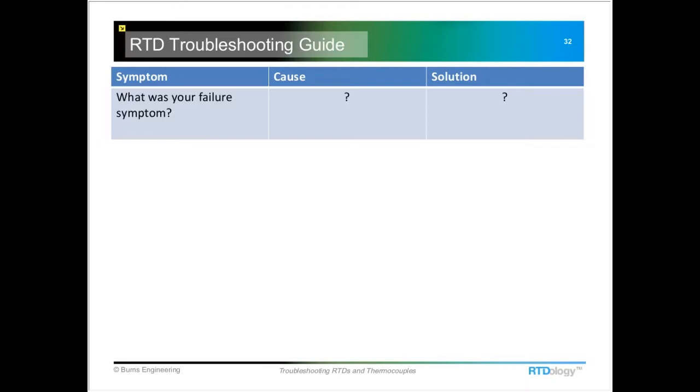Well, that's usually a permanent thing, though, where the probe is working well initially, and later they have trouble tuning that measurement loop because the time response of the probe slowed down. The probe got over-temped, and the potting material properties changed because of that, and it acts more as a thermal insulator than a conductor.